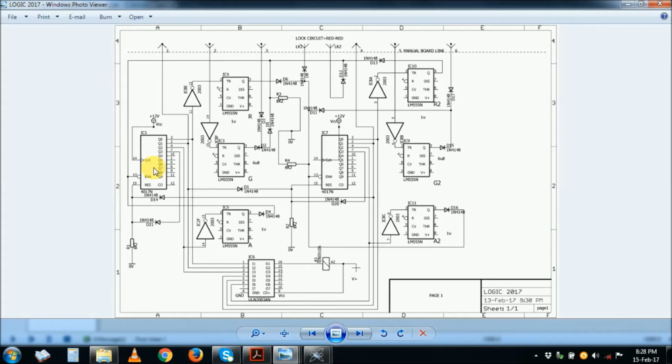The switch is not there because the switch is actually this output here, which will be transferred to the input. Remember, the input is going to the enable pin for the counter. It's not going to the clock, it's going to the enable pin. The clock input is wired straight to the power supply, pin number 16, so it's configured to actually step on the trailing edge as I have described in the clock circuit. So you have the transistor for triggering the monostable timer, and then you have the counter responsible for stepping, for switching the lights, and then the counter is wired straight on to the relay drivers for light output.